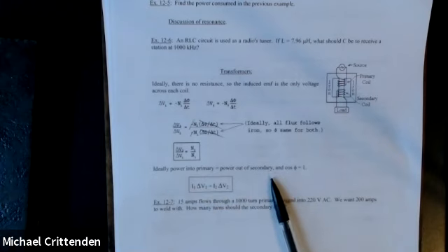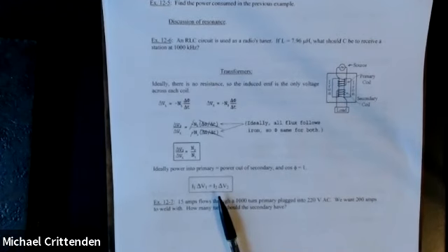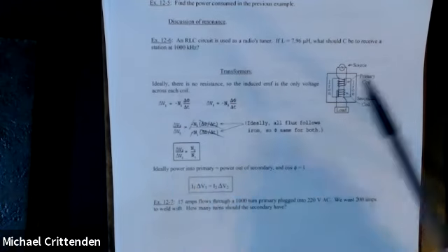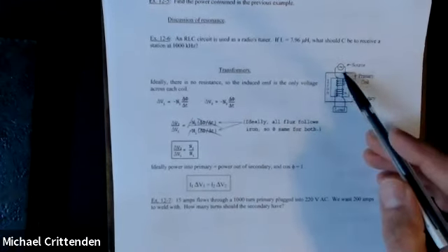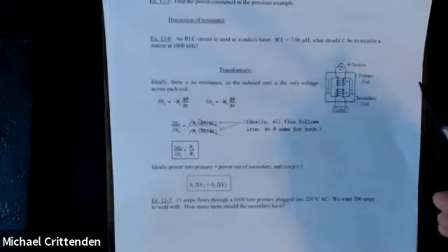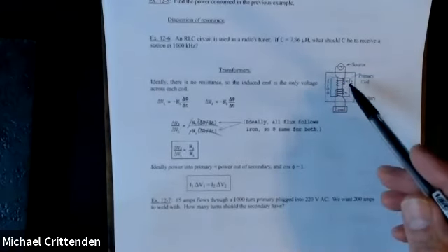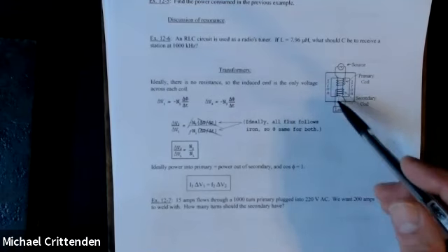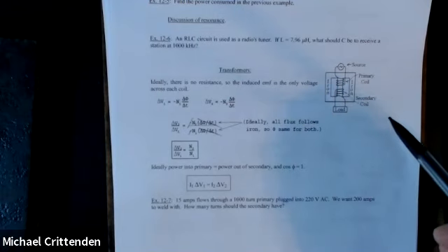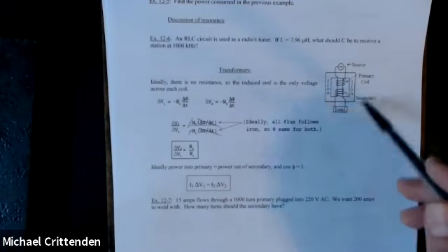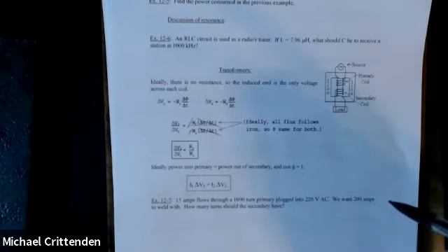Going along with that, you've got conservation of energy. Under ideal conditions, the amount of energy per unit time, which is what the word power means, being drawn out of these wires equals the amount of energy that's being put in through these wires. Now, realistically, a little bit of energy is lost to heat because of electrical resistance, and there can be eddy currents in the iron core that might cost you some energy.